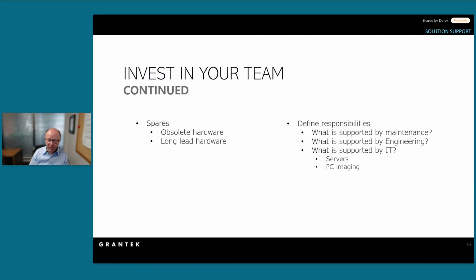But that 20 horsepower VFD that's running your critical blending system, that everything goes through, is a critical point of failure. Maybe that's a 2-month lead time, or we saw a couple of years ago a 6-month lead time. So with that risk assessment, you have to realize what spares you should keep to make sure that you can keep everything running.